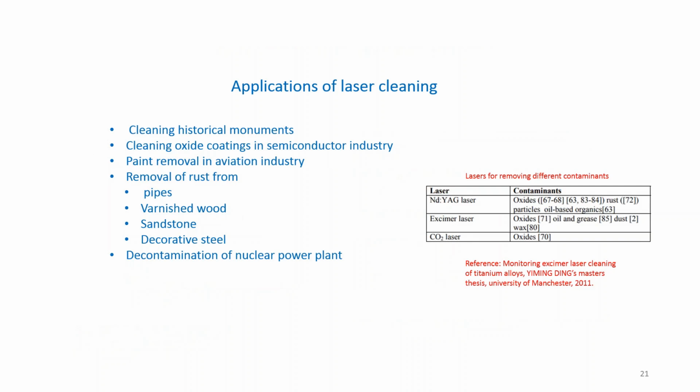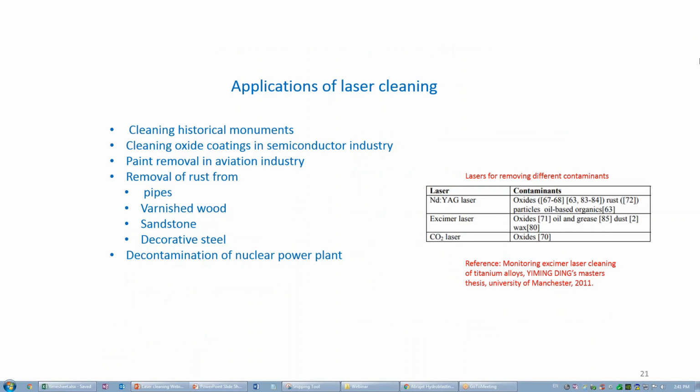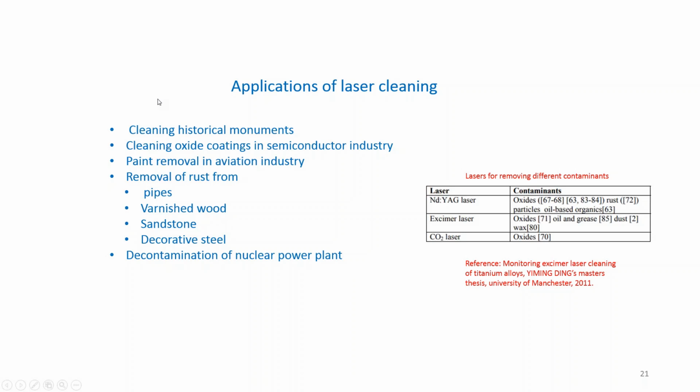Next, application of laser cleaning. Here we have, for example, for neodymium YAG laser, oxides, rust particles, oil-based organics; excimer lasers, UV lasers, oxide, oil and grease, dust, wax; CO2 laser, oxides. So cleaning of historical monuments, cleaning oxide coatings in semiconductor industry, paint removal in aviation industry, removal of rust from pipes, varnished wood, sandstone, decorative steel, decontamination of nuclear power plant. These are some of the applications, and we'll talk about some of them. I'll show some videos for each application.